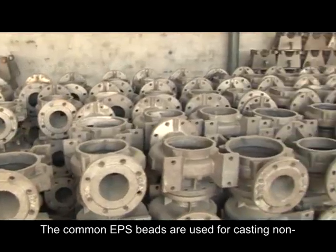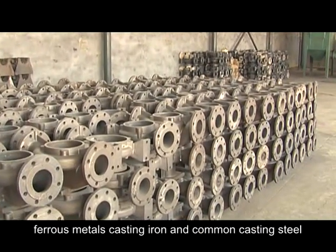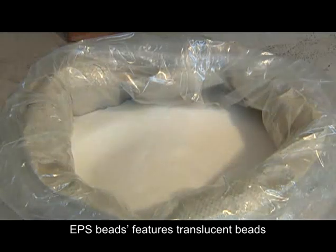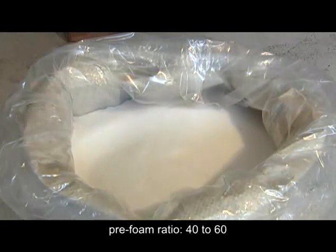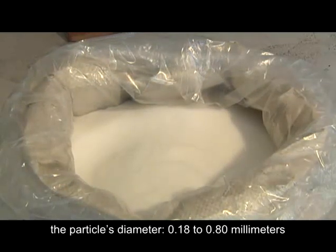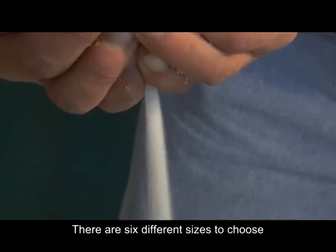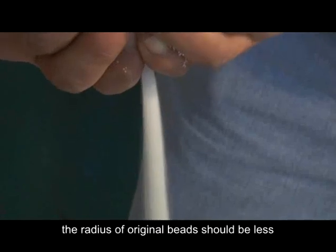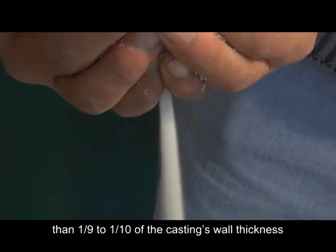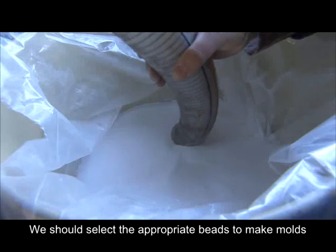The commonly used EPS beads are used for casting non-ferrous metals, cast iron and common cast steel. EPS beads feature translucent beads, preform ratio 40:60, and particle diameter 0.18 to 0.80 millimeters. There are 6 different sizes to choose from. The radius of the original beads should be less than 1/9 to 1/10 of the casting's wall thickness. We should select the appropriate bead to make molds.